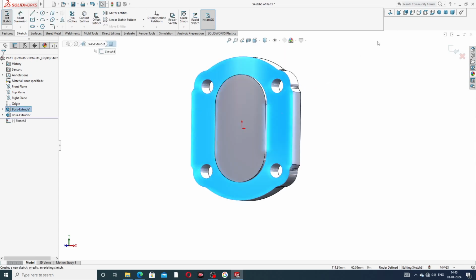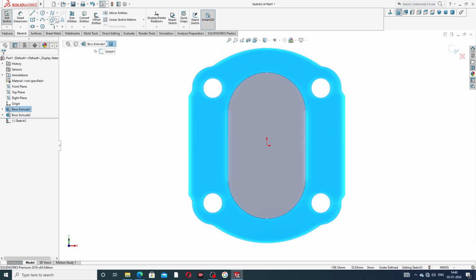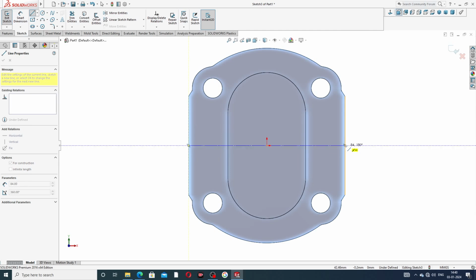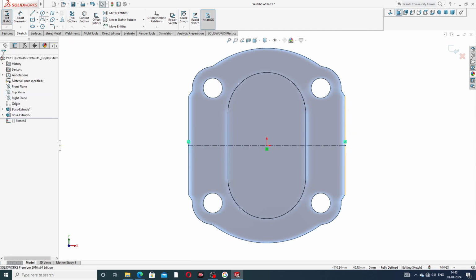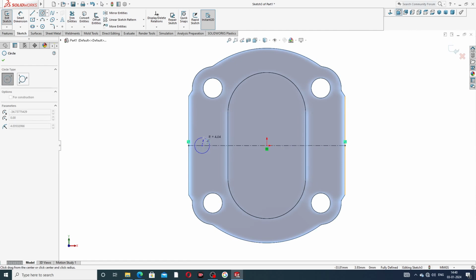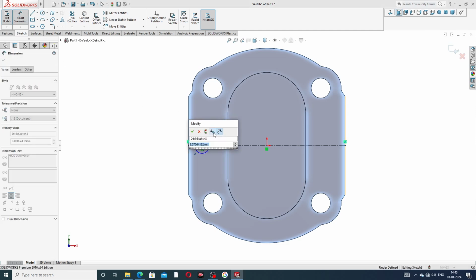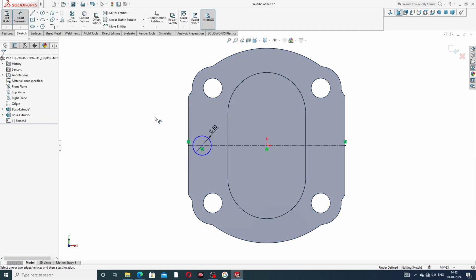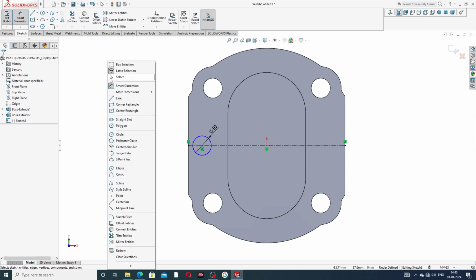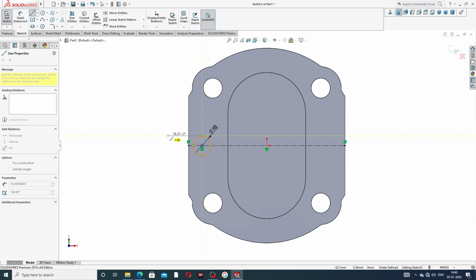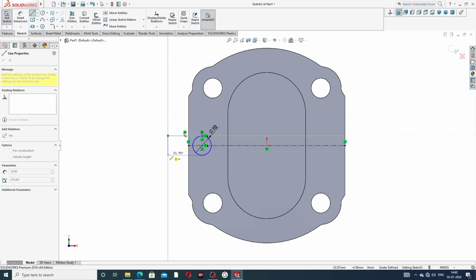This face, Sketch, Normal To. Draw a center line. Connect this midpoint to this midpoint. Okay, the circle is drawn here. This and this are 10 millimeter diameter. Okay, and the line is connected here. Connect to this point. This to this to this.